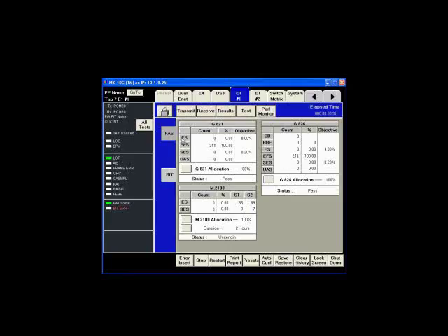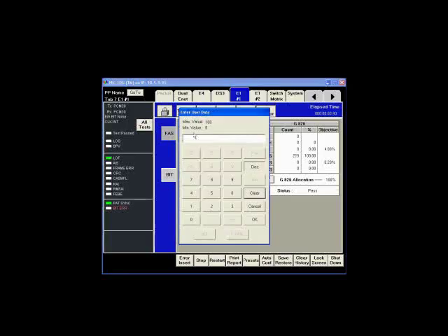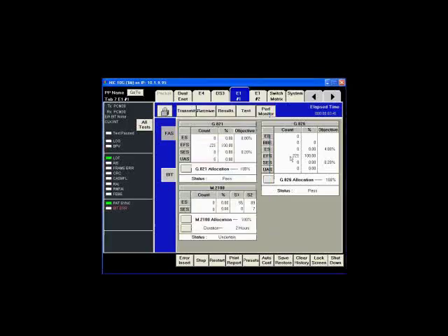And it calculates error seconds, error-free seconds, severely errored seconds, and unavailable seconds based on criteria in the standard. And these are optional, what percentage you want to use. 100 is basically standard. And it does this on the frame errors and bit errors.